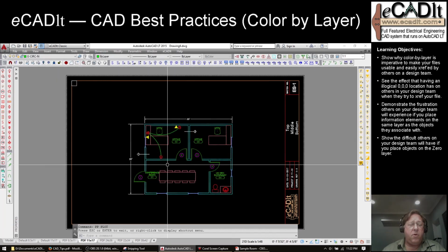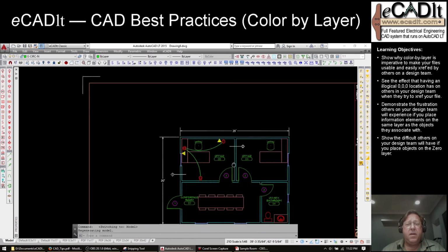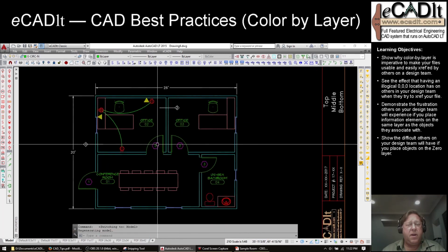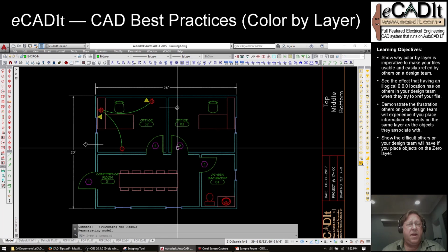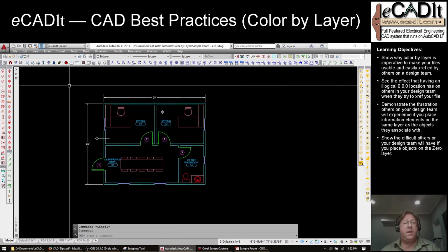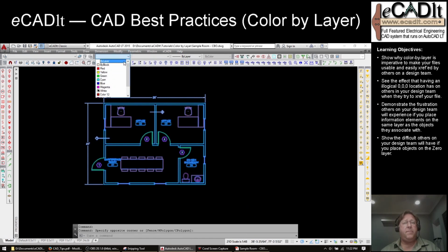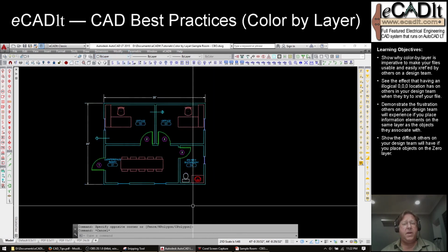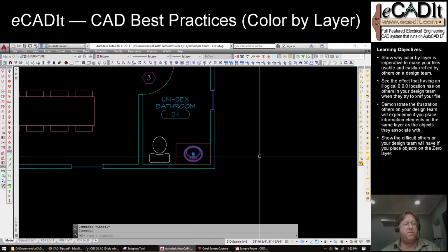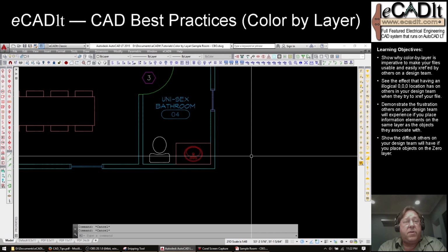I'm going to have to go back into this background file and delete things, change them, or work with them extensively to get them all to be color by layer. Now that won't be easy. Even if I selected everything and made it color by layer, that might help some, but these blocks that are made out of elements set to a specific color, I'm not going to be able to work with that. I'm going to have to pull open each one of those blocks and get them all changed to color by layer or something else.